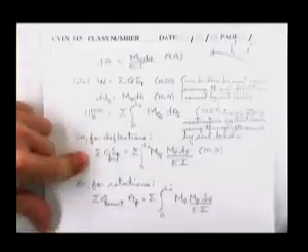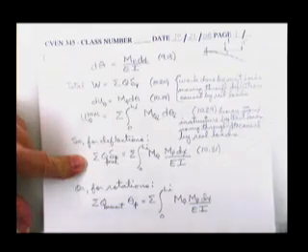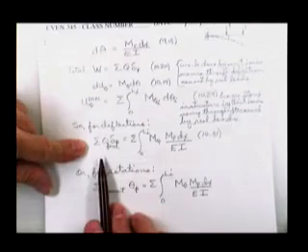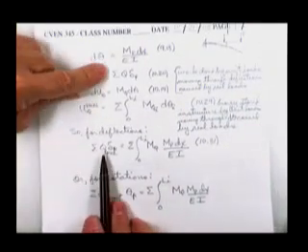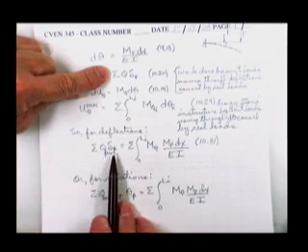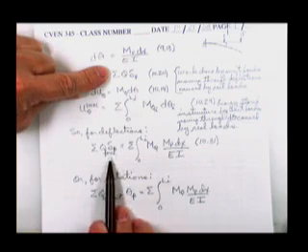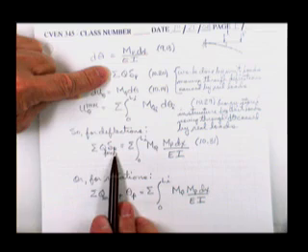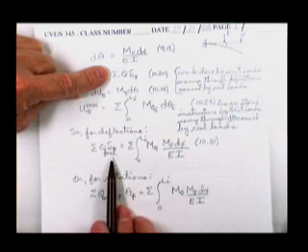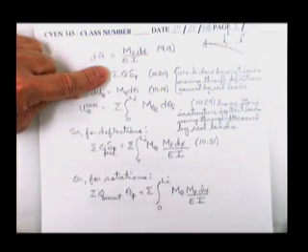So for deflections, we set how much work you did on it to how much strain energy got stored in the structure. The sum of the q, this is due to a force, times the deflection due to the real loads. And this will be a particular deflection because the terms that you will put in here, you'll put a unit load on here at a point of my interest and only one at a time.